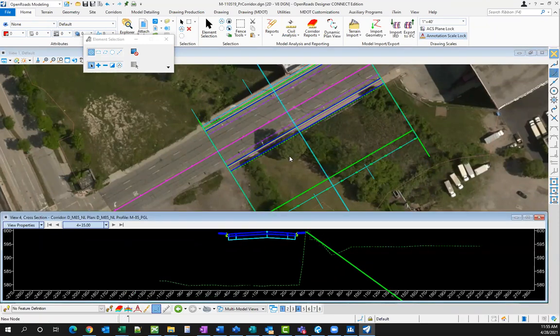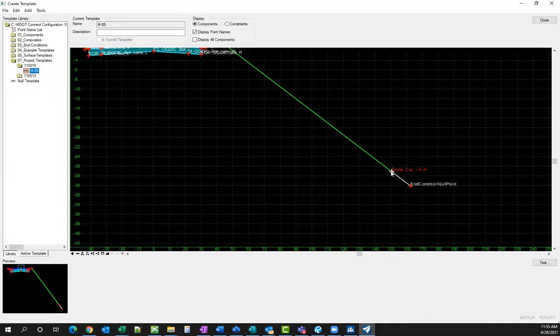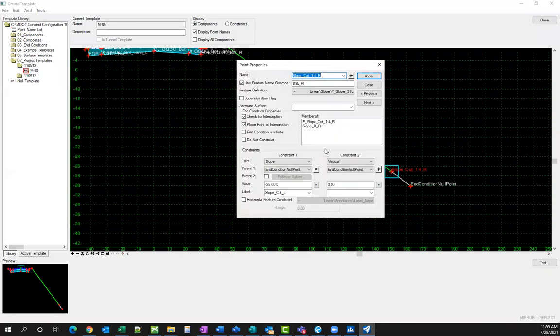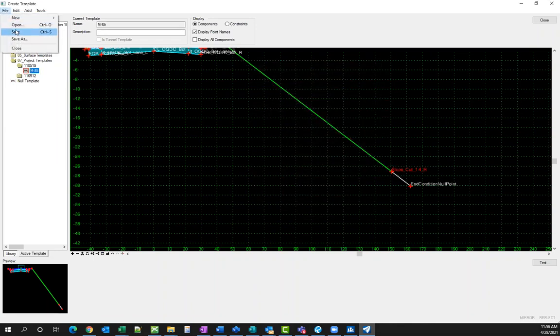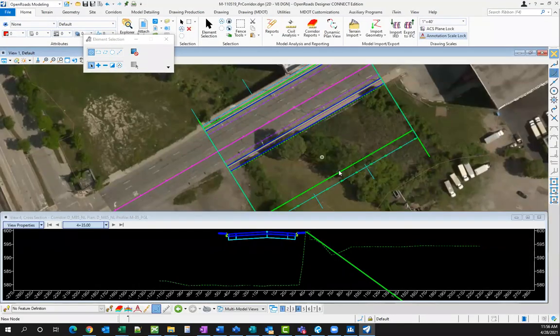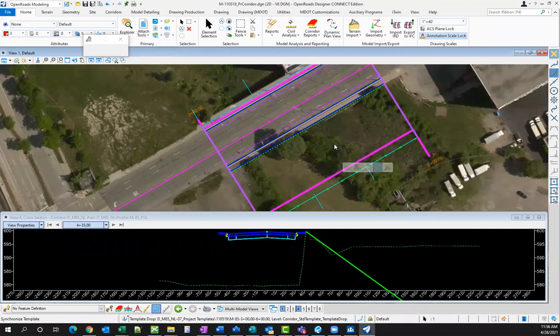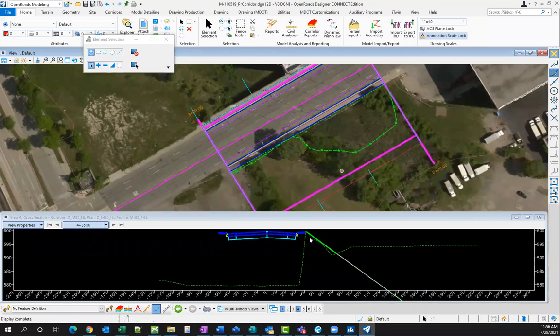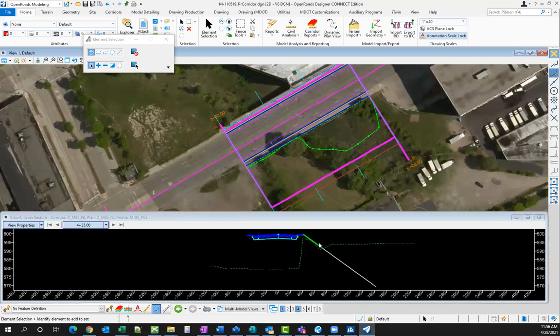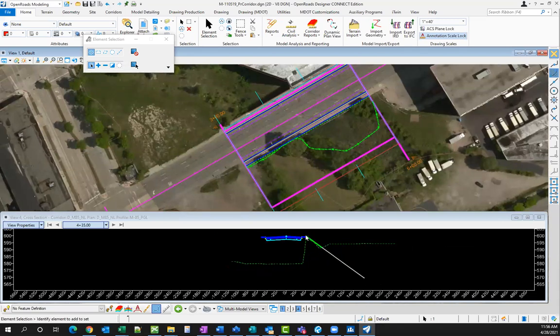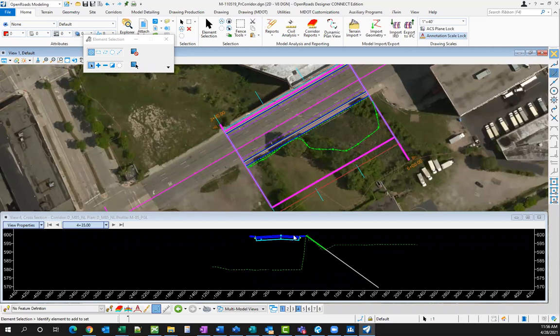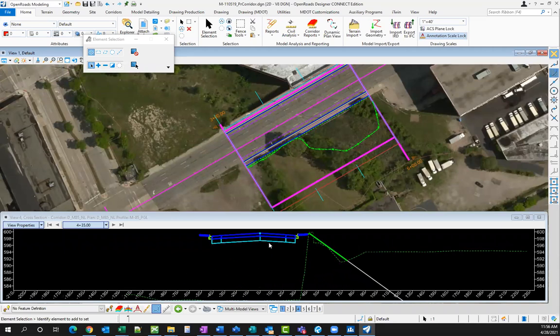What did I do? I know what I did. This component down here, I want to make sure that this is set to end condition as infinite, so it's going to search forever. And now when I synchronize my template, you should see, hopefully, the right thing. So now you have it. We have our do not construct component that's searching from the bottom, and our other component is going to find it from the top. So just kind of a unique thing. It's something I've run across a couple of times, and that's just one method that you can use to find that second solution.